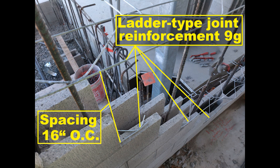Joint reinforcement. Factory fabricate joint reinforcement in conformance with ASTM A951. Provide ladder-type joint reinforcement, having 1 longitudinal wire in the mortar bed of each face shell for hollow units and 1 wire for solid units, and with all wires a minimum of 9 gauge. Size joint reinforcement to provide a minimum of 5/8 inch cover from each face. Space cross wires not more than 16 inches. Provide joint reinforcement for straight runs in flat sections not less than 10 feet long.